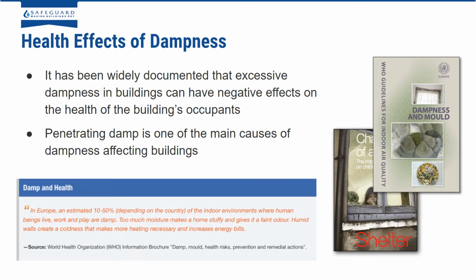So you could say that there's a good case for penetrating damp affecting the surface temperature of external walls, which in turn could lead to condensation issues developing internally as well. Yes, the idea is that the wet wall will become cold and allow the propagation of condensation.